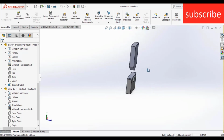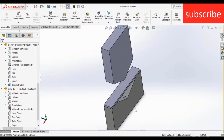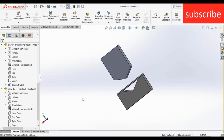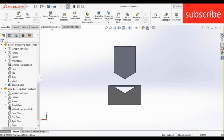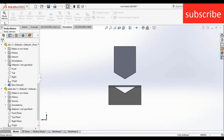Okay, after that I made this assembly. As you can see, it's properly assembled and it is totally coincident with the planes of the surface. Now after that, press Ctrl plus 8. Now go to Solidworks add-ins, click on Solidworks simulation. After that, wait a minute and you will see that a simulation tab appears. Click on simulation. After that, click on study advisor. Below the arrow, click on new study.